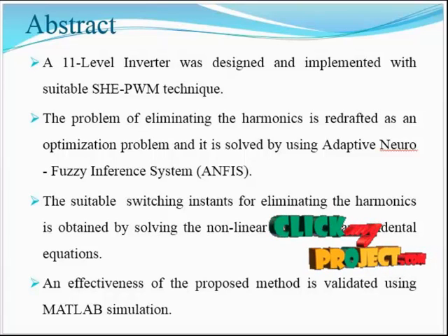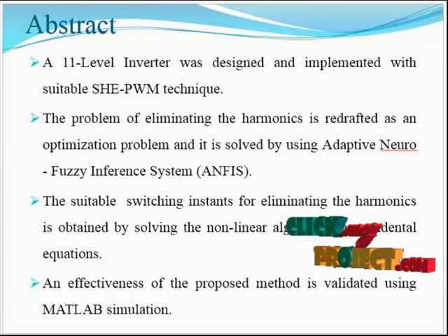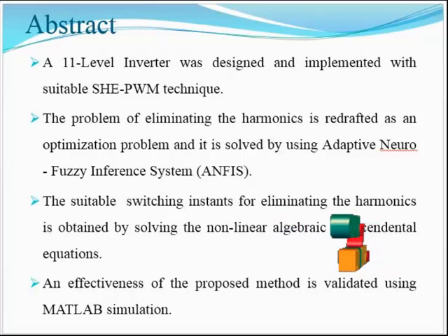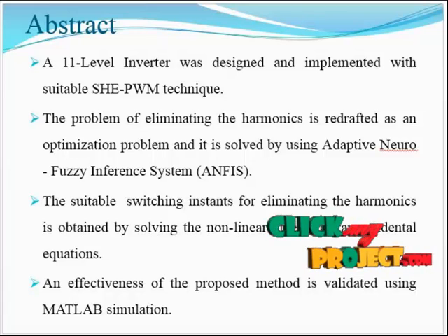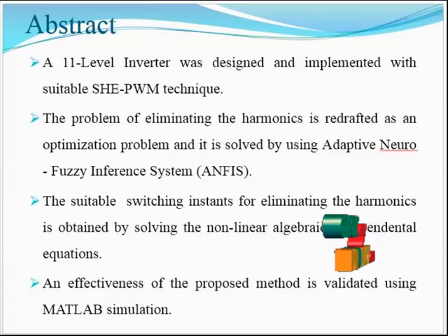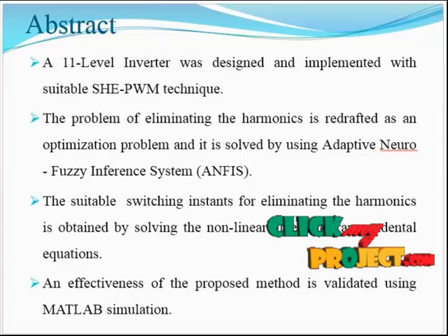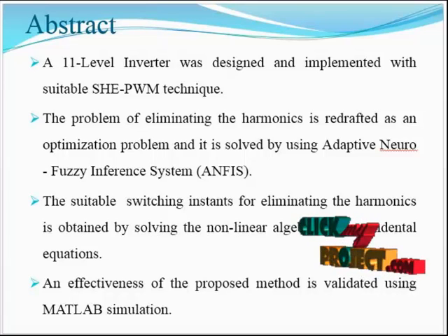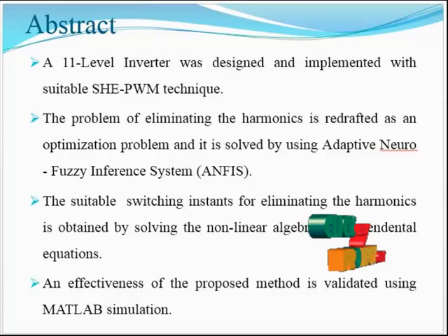The MATLAB simulation is carried out for various modulation index values. Finally, the switching instances corresponding to the PWM pulses are obtained for various modulation indices. These switching instances are compared with a triangular wave to produce the PWM pulses. These PWM pulses are applied to the inverter switches. Finally, an R load is connected to the inverter circuit and the FFT analysis validates the simulated results.